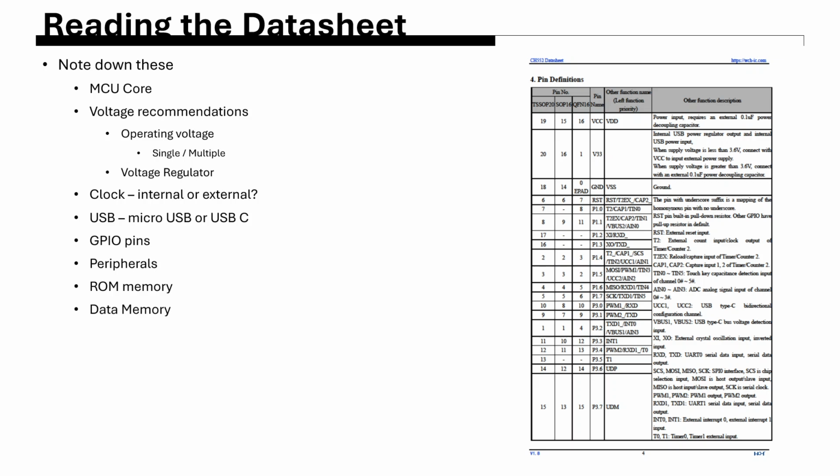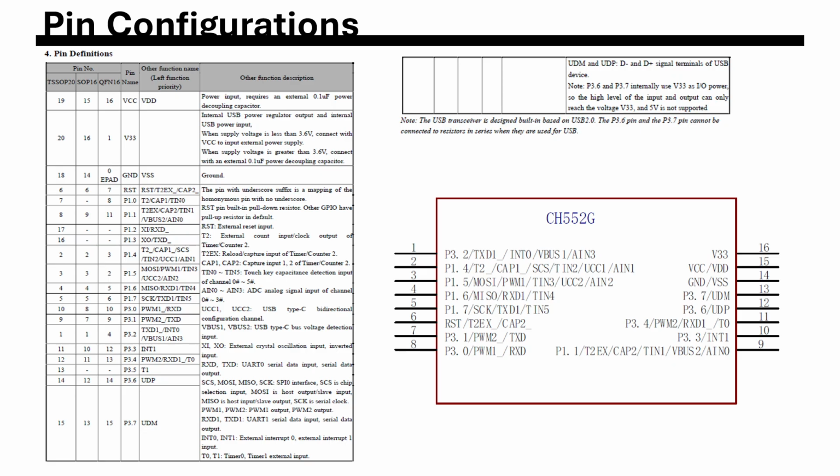Memory, we saw ROM memory, it had 16 kilobytes, data memory around 1 kilobyte, around 128 bytes RAM and 1 kilobyte of accessible RAM, right? Number of ports exposed are 2, and another one is non-exposed. In the exposed ports as well, not all pins are exposed, so we need to be very specific on those pins.